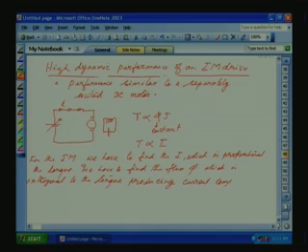In the separately excited machine, the flux and torque producing components are separately adjusted, but in the induction machine it has to be a vector sum.